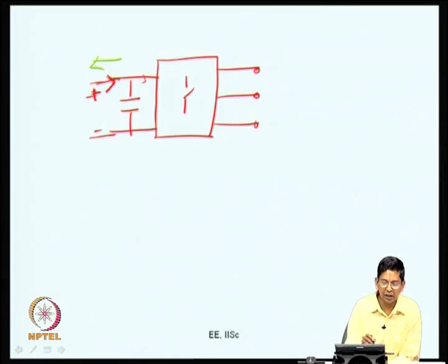If you look at the second case, that is the green ink one, you have on the AC side 3-phase voltages. The 3-phase voltages have their fundamental components. The 3-phase currents have their fundamental components. If you look at the fundamental voltage and fundamental current on the AC side, they may have a phase difference close to 180 degrees, between something like 90 degrees to 270 degrees. So, let us say around 180 degrees. So, that is a situation where power is really flowing from one side to the other side now.